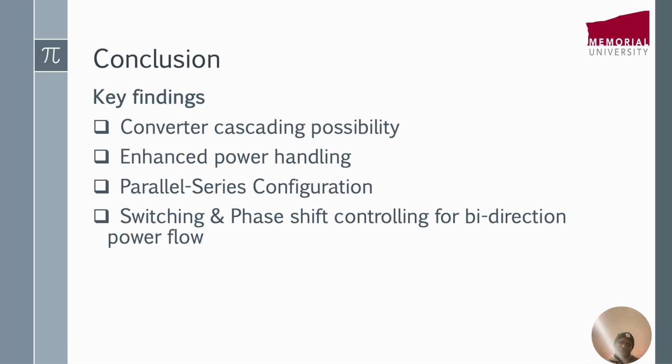And then one very important thing is that whenever we are dealing with dual active bridge converters, we must be mindful of the phase shift, because the phase shift determines the direction of the power flow. And also we need to create a sequence such that even with the series connection, we are able to give it that logical flow in terms of movement of current from maybe one converter to the other.